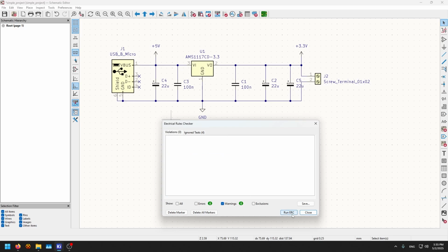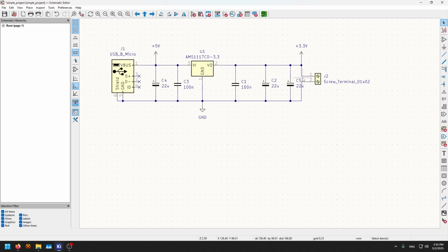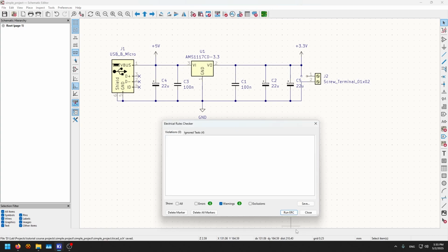So before you jump into the PCB, of course, you're gonna run the ERC check. You're gonna see this nice little 0, which is green, and hopefully no other warnings. But if it did, you need to tackle them. So let's make one, for example. Let's make something like this. This is now not connected. I'm gonna save it. I'm gonna say run electrical rules check. Now I wanted to show the errors and the warnings. It tells me that a warning, or maybe start with the error.